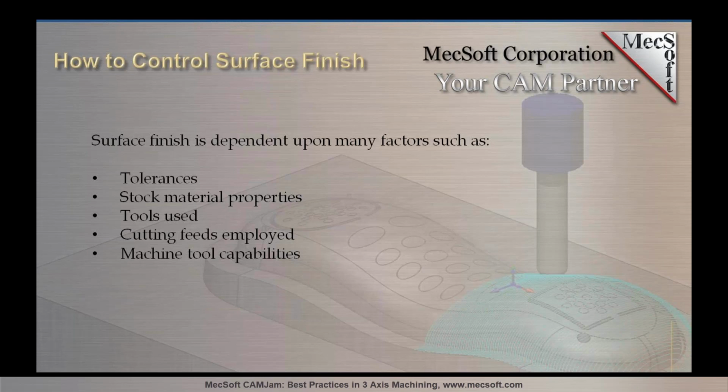And again, in the blog, we have some best practices that you can look at. A couple of the best practices I'd like to mention here before I turn it over to Uday is, you normally want to use machining regions that contain your toolpaths to flow with the geometry of the part. And then you can also use different cut patterns and directions of cut to obtain better surface finishes, and Uday will talk about that as well. So this part of the demo is going to be focused on surface finish and how you can control your surface finish.